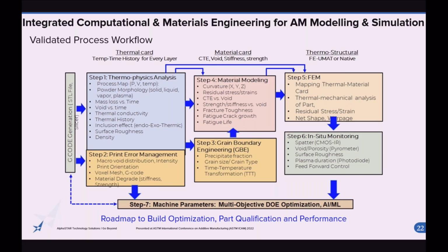Now, we also have a component we call our grain boundary engineering capability, and that involves inherent in situ variations to the build plan of G code, thermal cycle, inherent heat treatment that can impact cooling, heating, thermal cycling, ultimately impacting grain architecture. That's an advanced technique, but it's a capability that is under continued development. And again, all that information can be bundled into our analysis or modeling to understand an as-built material model over time, including nonlinearity for this particular build set.